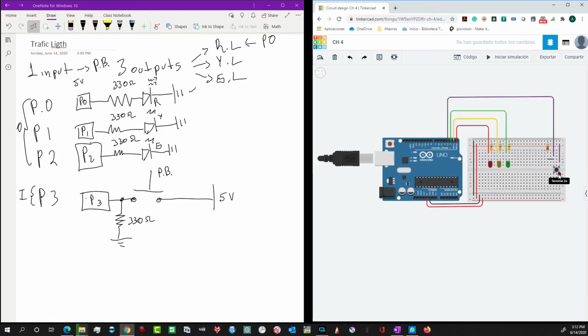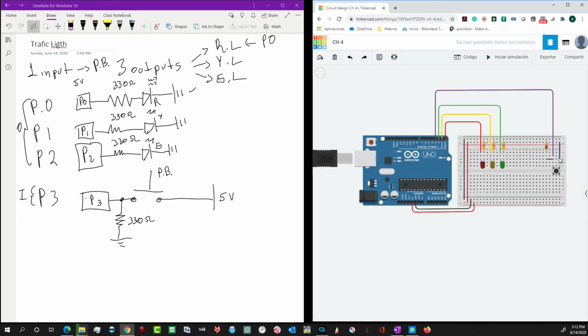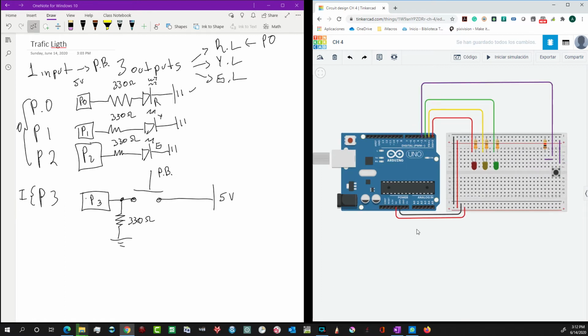So this is almost the same as I told you in the previous video. I need to provide a negative connection, you see, the GND port from my Arduino card to my breadboard. And as you can see, I have electrical connections all along this line. You see, if I put any connection in here, I get this red notification. This means that I have electrical connection on all these lines.